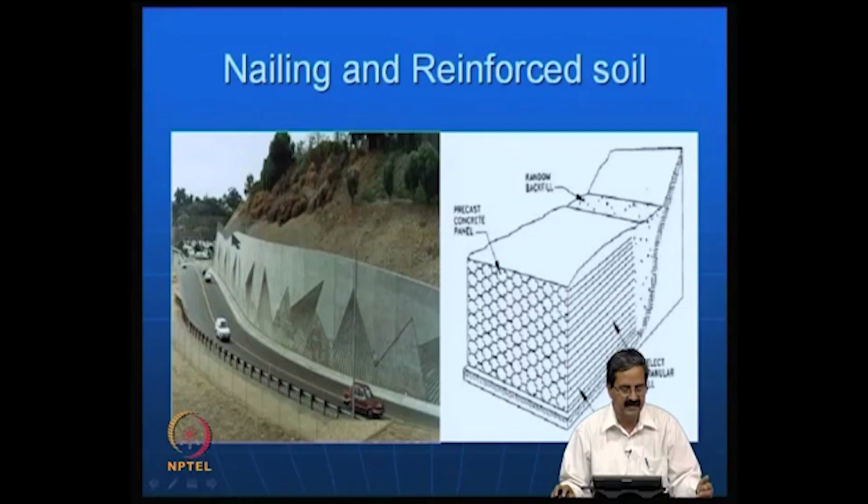So, this is a very classical example of how you use native soil and make it stronger. There is no point in trying to disturb the soil and then replace the soil. Whatever is the existing soil, try to understand the soil behavior properly, find out the soil properties properly. If it is not strong enough, like it has a tendency to collapse, calculate how much reinforcement is required to make it stable, that is all. So, this is what we did here, what we can do in many cases, and this is actually a technique called the reinforced earth technique.